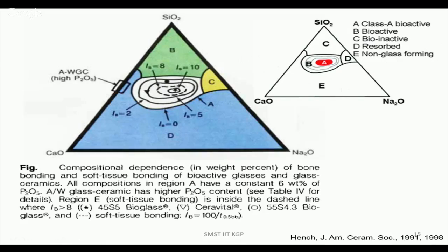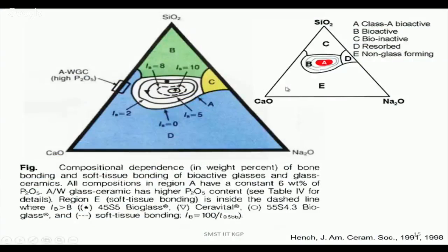very long chain, covalently bonded, alternate silicon-oxygen-silicon-oxygen-silicon-oxygen network, and these single valence ions, cations, work like a network breaker. They break down this Si-O-Si bond and come in between. So that is why, if you have too much sodium in the glass, the glass property will not be there. It doesn't form a good glass. Okay, so that is why it's a non-glass forming material, because you have too much sodium,